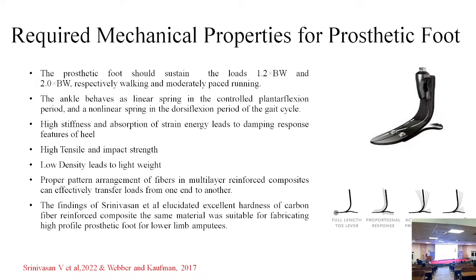So what are the required mechanical properties of the prosthetic foot? The prosthetic foot demands that it can sustain loads of 1.2 times the body weight during walking and 2 times the body weight during running. So the angle during the gait phase, because we need to vary the stiffness properties. During the controlled plantar flexion period we need to adjust the stiffness, and during the swing phase of the gait cycle, the ankle behaves like a non-linear